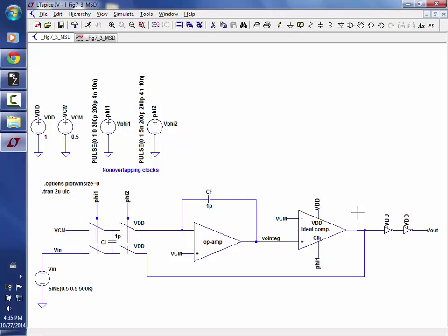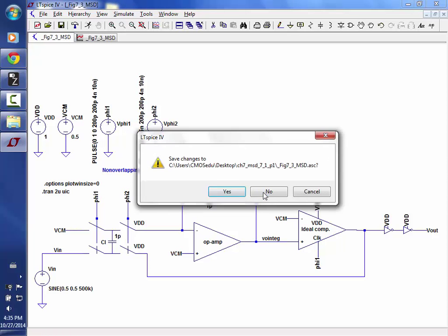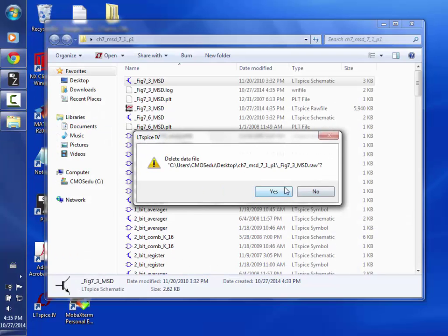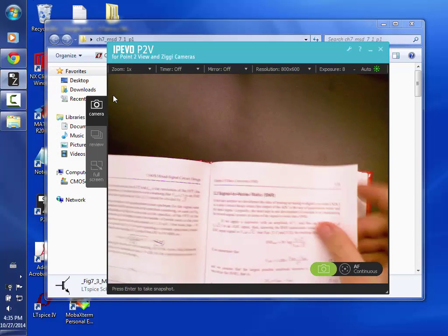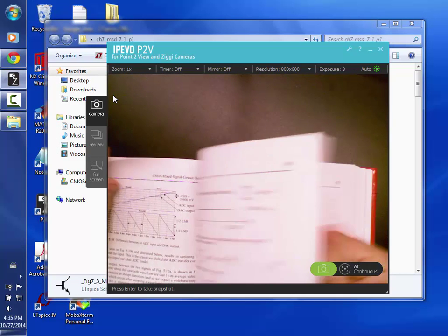That's one of the big reasons why single-bit quantizers are used, because if you have a multi-bit quantizer, if you remember, it's harder to adjust the gain. You're basically limited, okay? And just to make sure everybody follows that, we'll look at the book. Let's see, where was that? In like chapter 5 maybe?